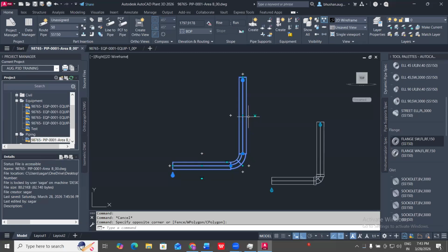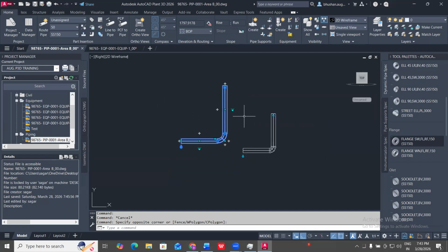If you want to add a whole pipe, not elbows or any fittings, you can use the bends at that time. But if you are using elbows in your piping, then you will not be using the pipe bends option. So mainly, pipe bends can be used where you want pipes which need a radius more than your standard elbow.